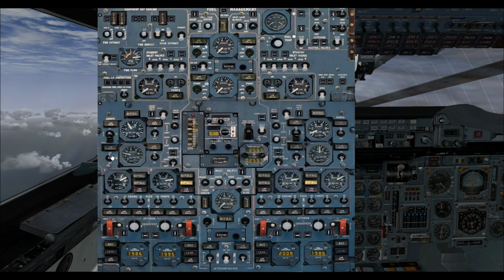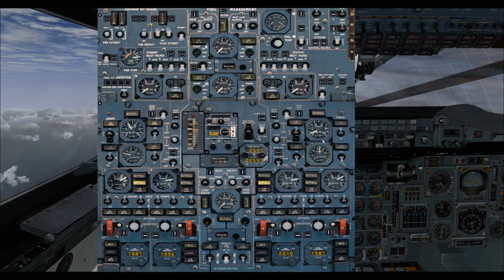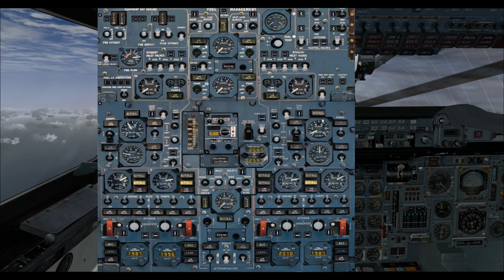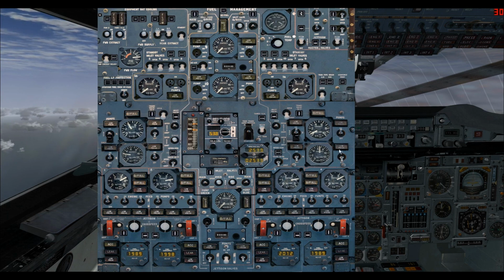Okay, so this has been going for a while now, and as I indicated, because we've been jettisoning fuel from the rear tanks, the rear main tanks, our CG has moved forward to 53.8, and we're coming to the end now on tank 7, and still a bit left on tank 6. So probably what I would do here is stop the jettisons from 3 and 4 and continue from 1 and 2 for a little bit.